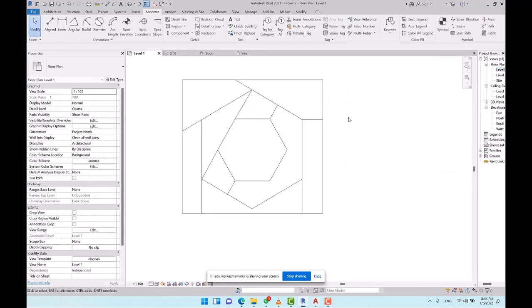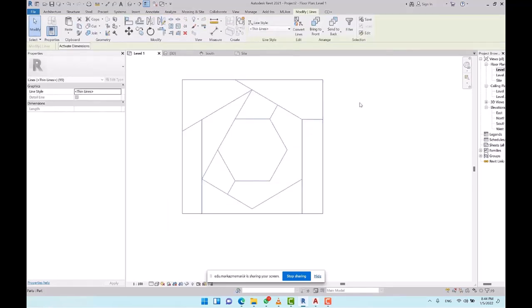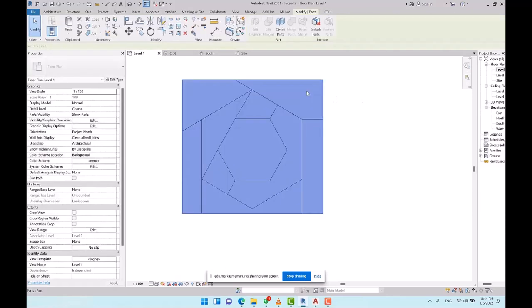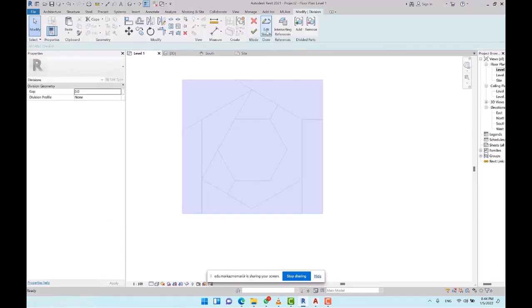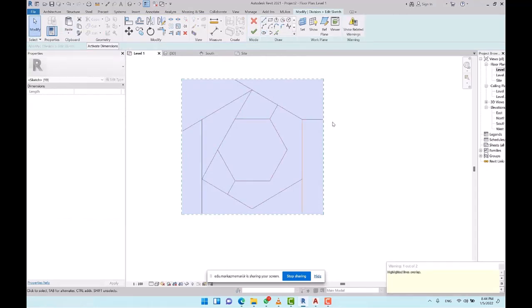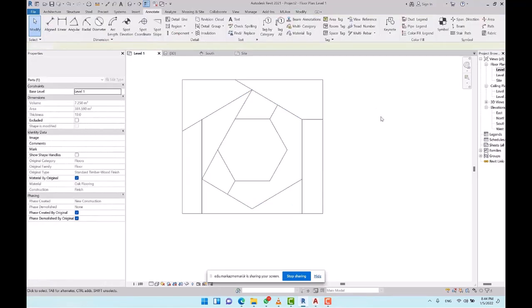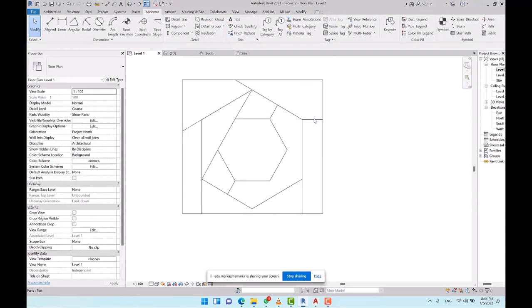I select all of the existing lines, then I choose lines in filter. I make a copy. By this way, I click on divide parts and edit a sketch, and then I paste the sketch lines in edit sketch command so that the pasted lines will be considered as sketched lines. I click on finish to divide the parts. Check it out. Here is the result. As you can see, as I hold the mouse, the boundary lines are highlighted. That shows the different parts very well.